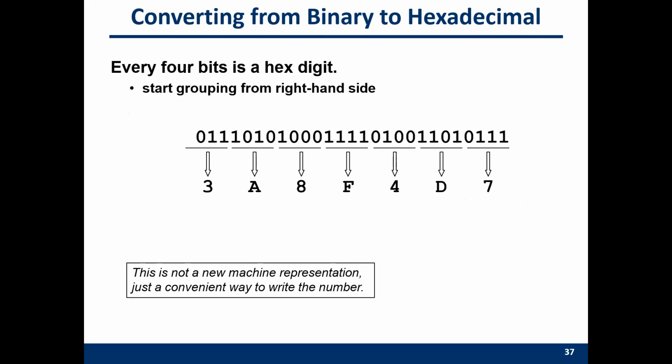So here is one example. The conversion from a binary number to a hex number is very simple. You just convert each 4 bits to its hex. This is a 7. This is the D. How to convert these 4 bits to this one? You can use the same algorithm which converts the binary to the decimal number. Because you only have 4 bits here, this is 2^0, 2^1, 2^2, 2^3. For this particular region, then this is a 7.